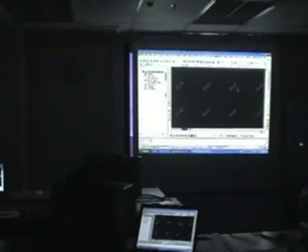A very common problem here in Malaysia is that most consultants receive drawings from the surveyors in this format, where you only get a 2D format. It's just a drawing. Maybe you've got points or just text, but you don't actually have points in your 3D positions. The Z values are not there. That becomes a problem because most software in the market now, you need to have the 3D value before you can run any functions at all.